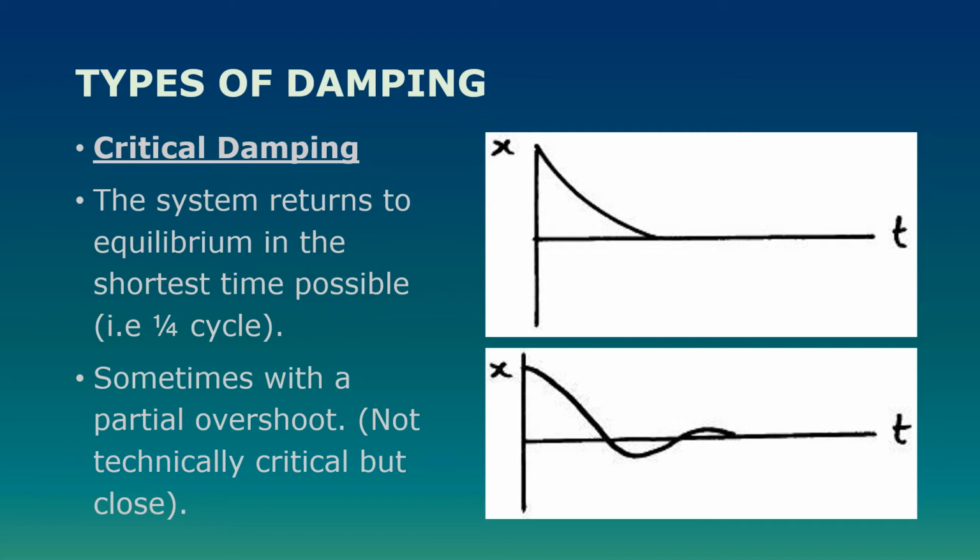And you can imagine that like a slamming door almost. It's at an amplitude, you shut it, but it slams shut, and the damping force there is the catch getting hold of the door and stopping it moving. So it stops it dead. Now, that is a very specialized case for that happening. It does happen, and it happens, as we said there, in just a quarter of a cycle from amplitude to equilibrium and stop.